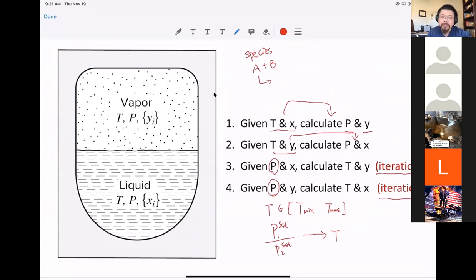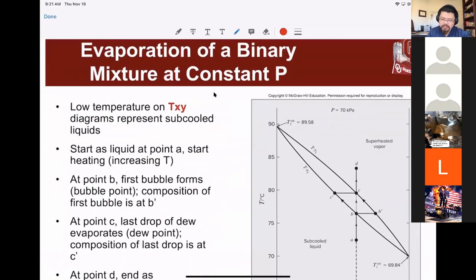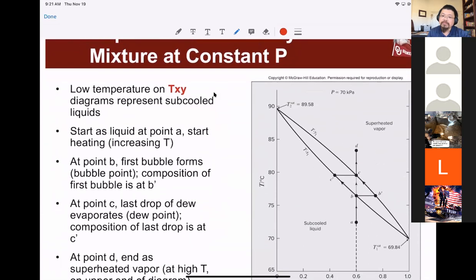So including the critical properties, including those omega values, including those ABC coefficients for the Antoine equation, so that we should be able to figure out P, T, X, and Y. So we are able to determine the exact composition of the system at any temperature and pressure. So this is indeed how we can construct the phase diagram.